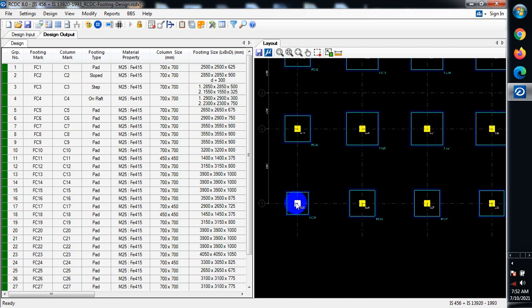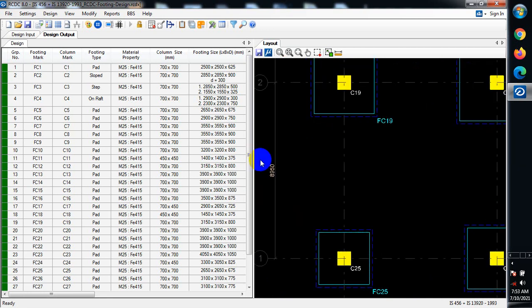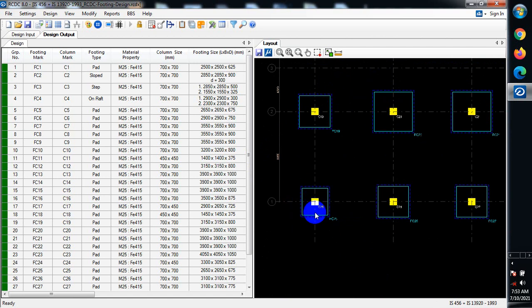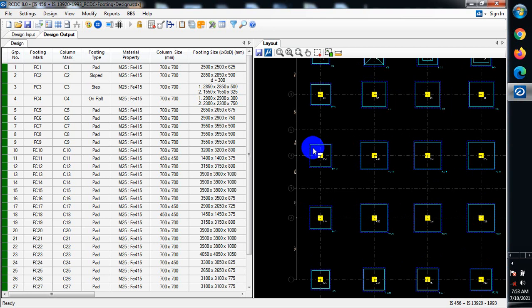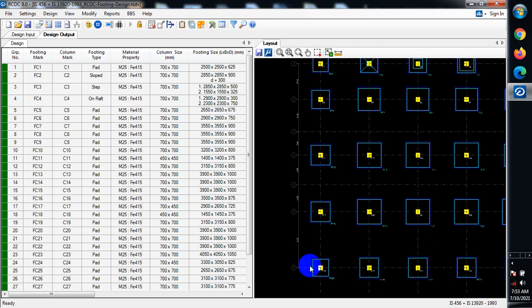What that means is that it's carrying only this load along the span, half of this is also carrying half of the load along the span. So it's actually not carrying as much load as the one that is here. So the column here is definitely carrying a higher load than the column which is here.